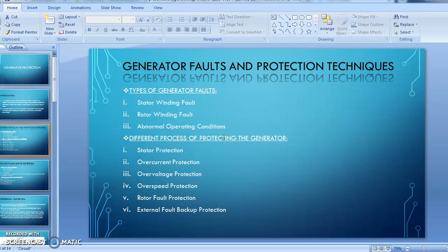Secondly, unbalance may occur due to a single-phase fault or unbalanced loading. That means if different types of load are connected to the alternator and those loads are not balanced practically, there will be unbalancing created. Open circuit due to a broken line or failure of one pole of the circuit breaker to close, although short circuits will normally be cleared by circuit protection. However, uncleared faults and unbalanced loading arising from the foregoing can occasionally maintain an unbalanced current condition in the generator.